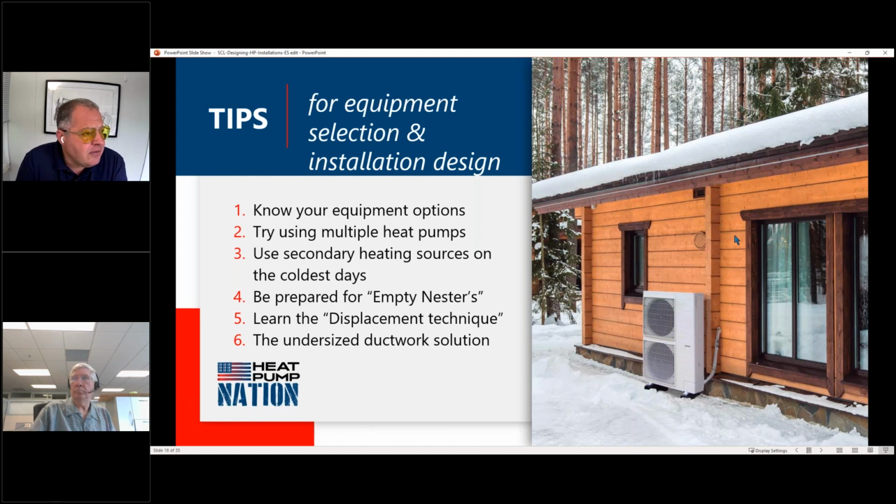So what I have learned to do is look for some reasonable best indications about the home to determine ductwork leakage and infiltration rates, those two very important settings within the load calculation software. And I make best guesses that are educated on some indicators. This is a whole subject matter, Robert, to go into. So I'm not going to go into it, but it's a good question.